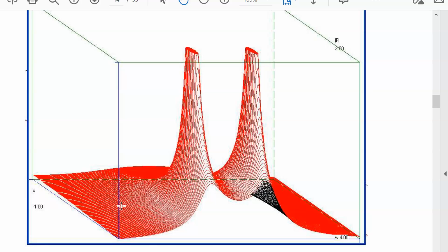What is interesting about this mesh plot is, now look vertical over the omega axis, then you can see the gain of the filter. Here the gain is small, it's 0 at 0. For DC we have no gain. Then there is a gain increase with 2 peaks, and then for higher frequencies the gain goes down to 0. So here you can really see the bandpass filter function of this filter.